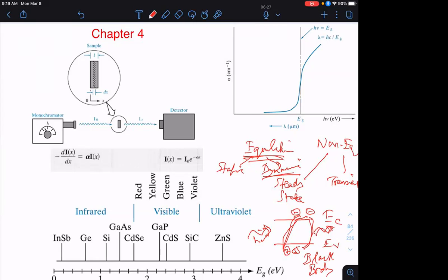So this is a constant exchange of energy between the semiconductor and the ambient. And that's in fact what creates this intrinsic carrier concentration n_i, which at room temperature in silicon we saw is about 10 to the 10 per unit volume. Now, of course, if I had doping, the picture gets modified because then the donors can create extra majority carrier electrons at the expense of fewer minority carrier holes, and so on and so forth. It's still equilibrium, but it's dynamic equilibrium. It's not a static equilibrium.